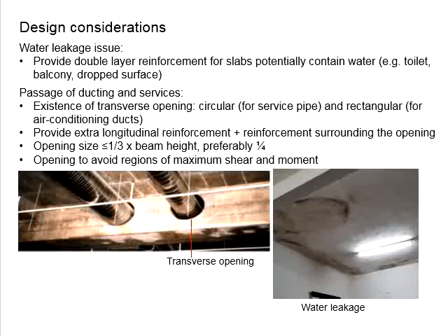You need to know the functionality of the structures is also a part of the design. There will be occupants in the building and there will be usage of water. You know that concrete is not totally waterproof unless it is properly designed. There are requirements in the Eurocode in terms of the design, controlling the crack width as a measure to control the leakage of water, which in this case, you will need to design accordingly.